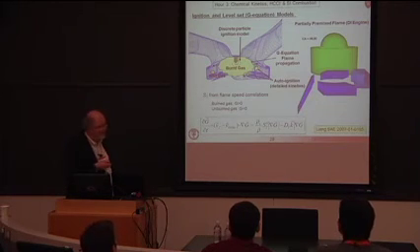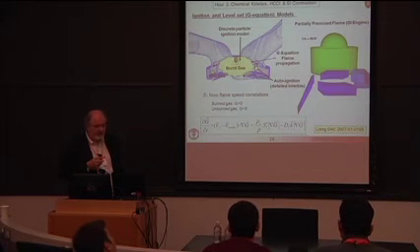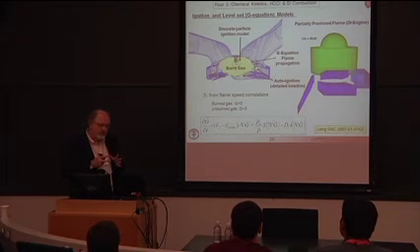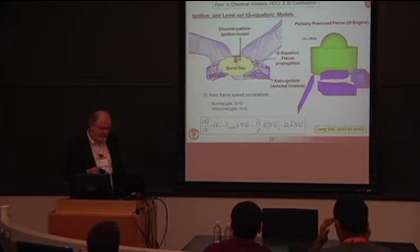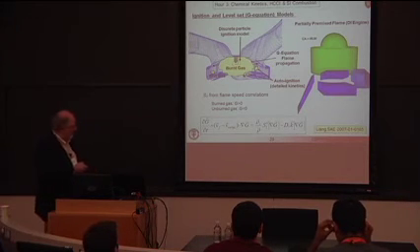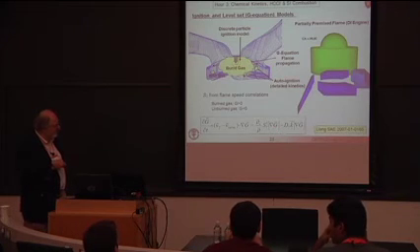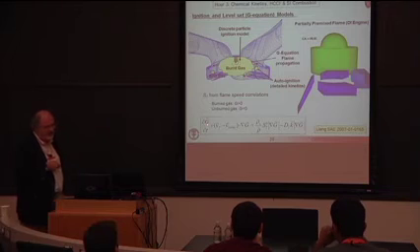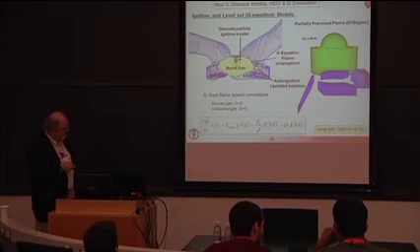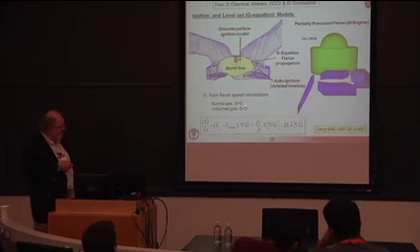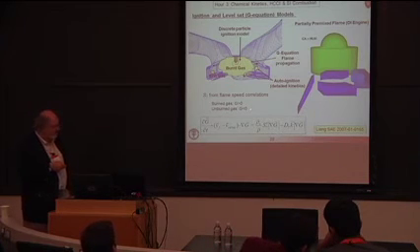So we use a particle approach, and I'll tell you more about it a couple of slides from now, where the particles represent the growing flame kernel. When they reach a size that's big enough, we then transfer to the G equation solution, and that's this equation down here. So what we're calculating is this parameter G, which is, as you'll see in a minute, arranged so that the burnt gas has G greater than 0 and unburnt gas has G less than 0.